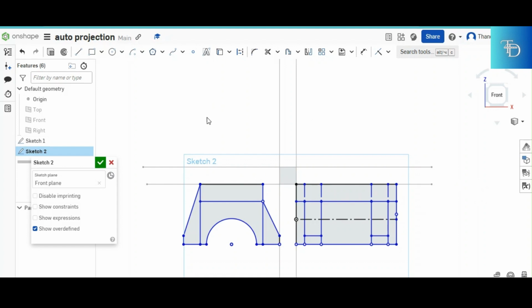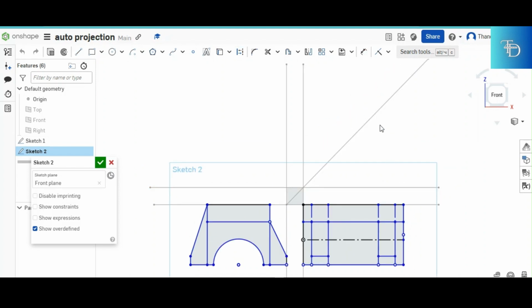There is an empty space for the top view there. It's supposed to have a top view up there. The next thing that you do is you produce a 45-degree line that starts from where? From this corner, from the top right corner of the front view, and it goes in that direction. It makes an angle of 45 with what? With the horizontal. So there is your starting point, the top right corner, our special corner. You take a 45-degree line, just like that. So there you have your 45-degree line completed in faint line there.